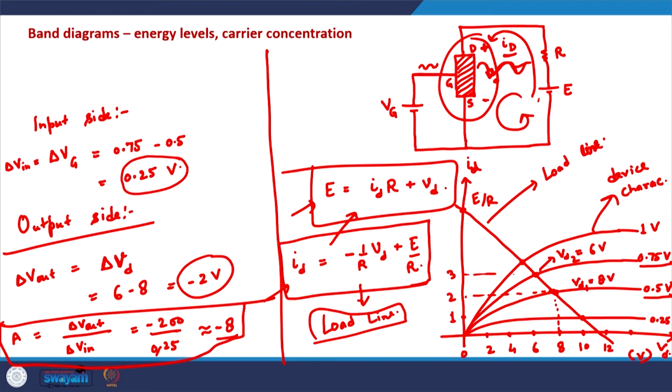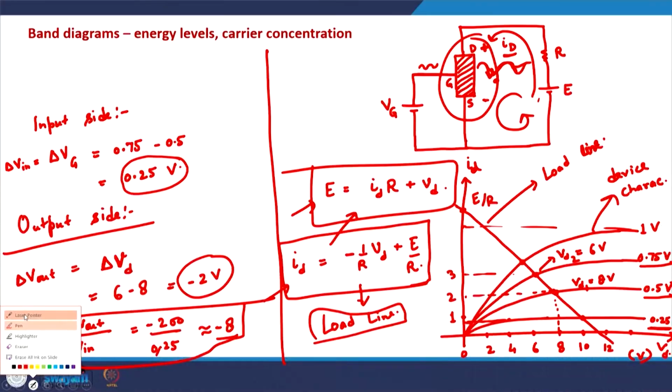Okay. Similarly, the switching can also be understood from this plot, although switching is clear from the device design as well. When the gate voltage is 0.25 volts, the current across the device is very low, and when the gate voltage is, let us say, 1 volt, the current is extremely high. So, just by changing the gate voltage, we are able to switch from a low current state to high current state. We are able to switch on the channel in the device so that the current can flow.